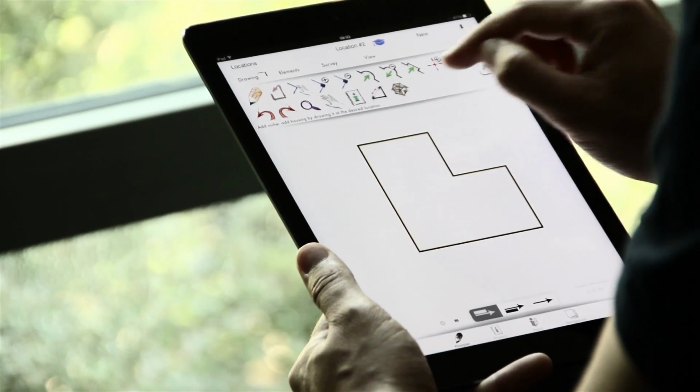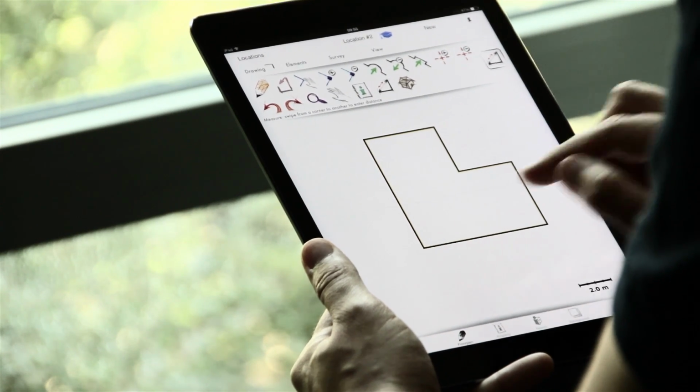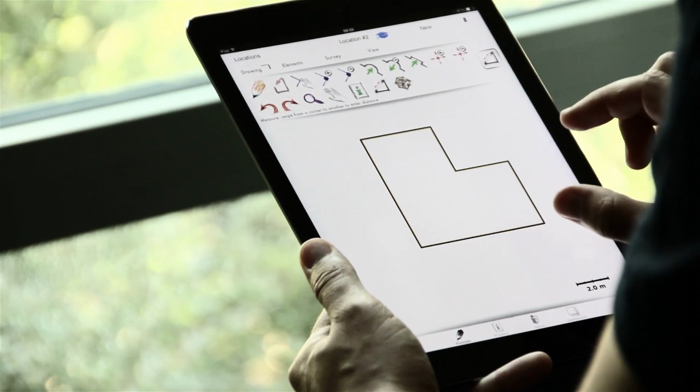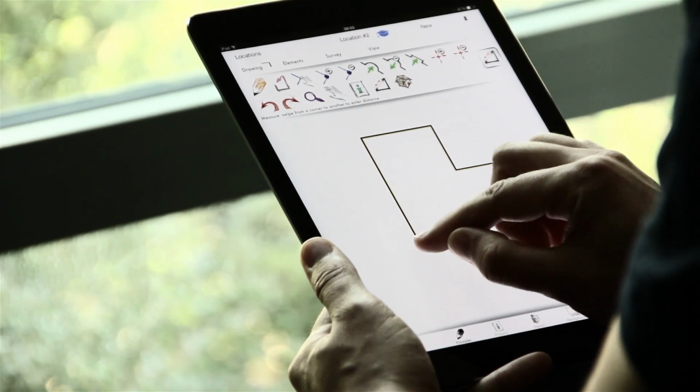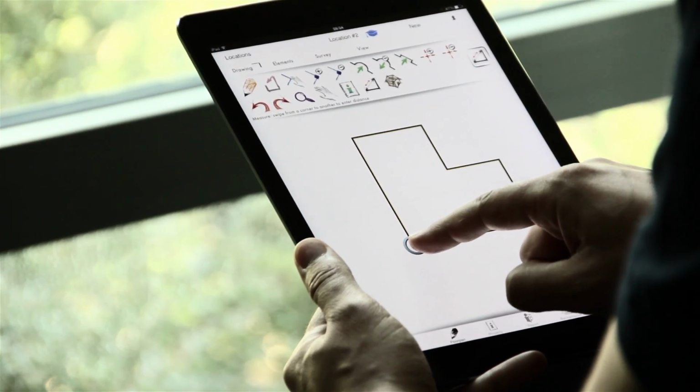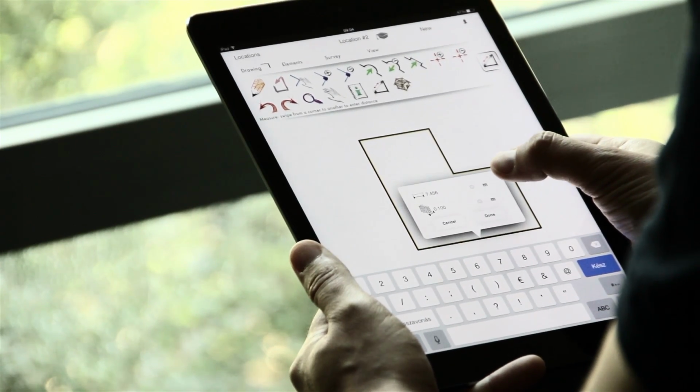Next thing we do is that we start measuring the drawing. The first measurement we place is going to rescale the drawing while keeping the angles and corners unchanged. OrthoGraph tries to maintain the angles as long as it's possible. If you measure diagonals, it will change the angles too. Let's illustrate. I make this measurement down here, click and drag. It tells me it's 7.4 meters.